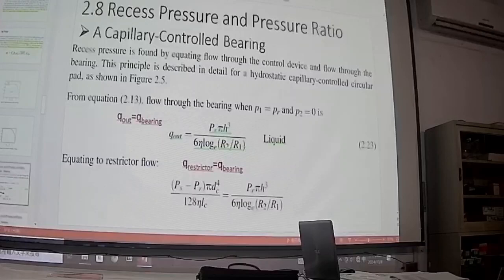Chapter 2 is the only chapter for the theoretical part of the design theory. Not so difficult. In chapter 2, it is basically only the air bearing that is introduced. It's not so complicated a Reynolds equation. It's just a two-dimensional Reynolds equation, written in a simple form, and it's a special case, so it won't be too difficult. If it introduced three-dimensional flow, it would be more difficult. So you should read the text.